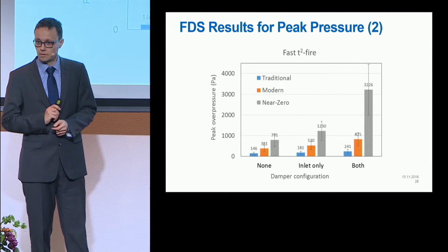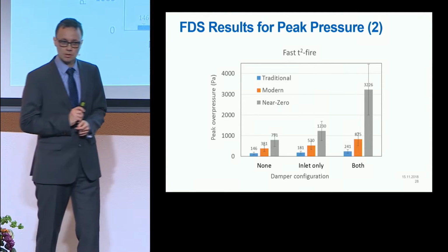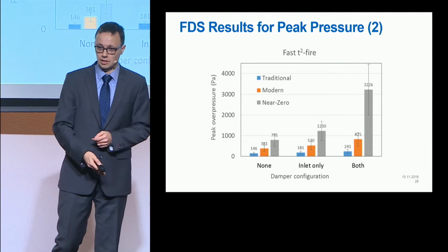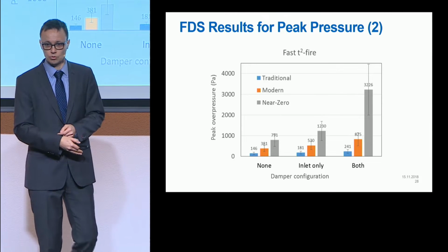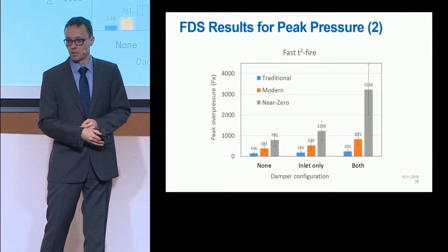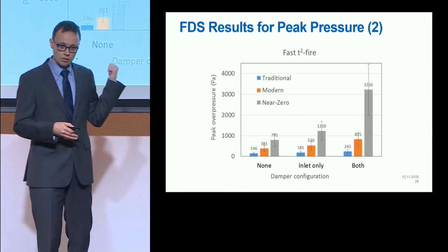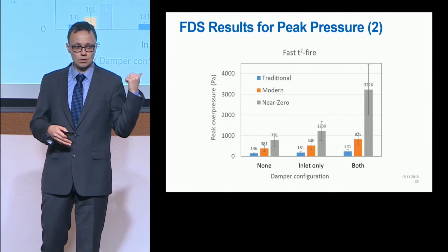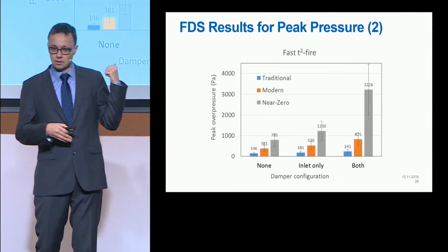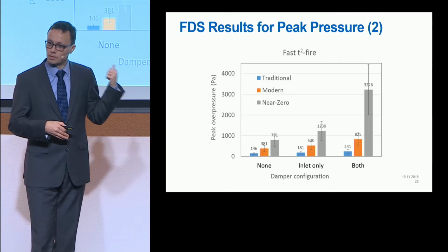What if the failing structure is between the burning apartment and the staircase, which we usually assume to serve as an escape route for the other occupants of the building? It means that such an overpressure could cause a loss of fire compartmentation and the usability of escape routes.